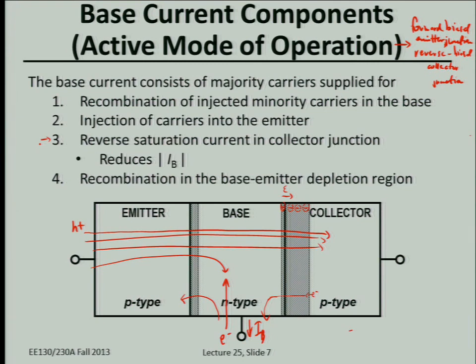And then recombination. So remember some non-idealities of p-n junctions. When you forward bias a p-n junction, not all of the current, yes, that will lower the barrier to allow diffusion across the junction, but some of those carriers can actually recombine in the depletion region, so some electrons end up recombining with some holes. That's just a non-ideal effect that shows up at low bias, right? Low forward bias, where it becomes significant.